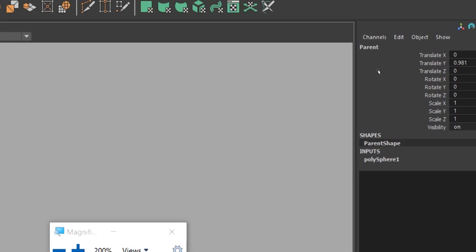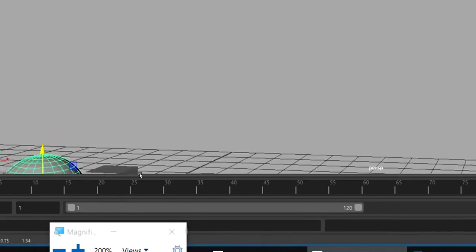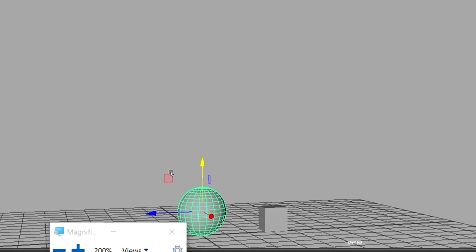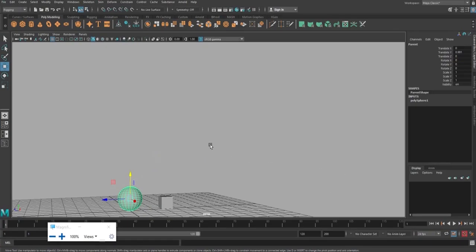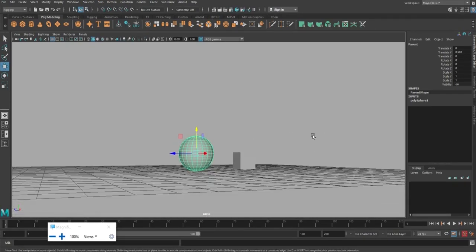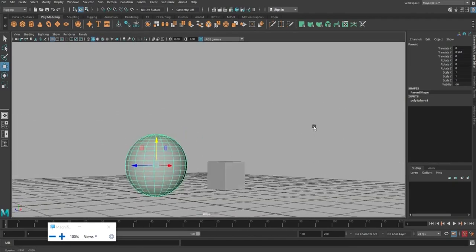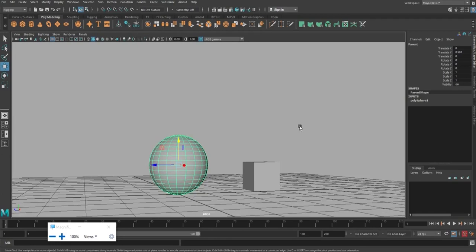So in rigging, before giving any connections or inputs or connectivity, what we need to do is reset all the transform and rotate values to 0, so that it will be very clear and easy for us to identify the global position of any object.